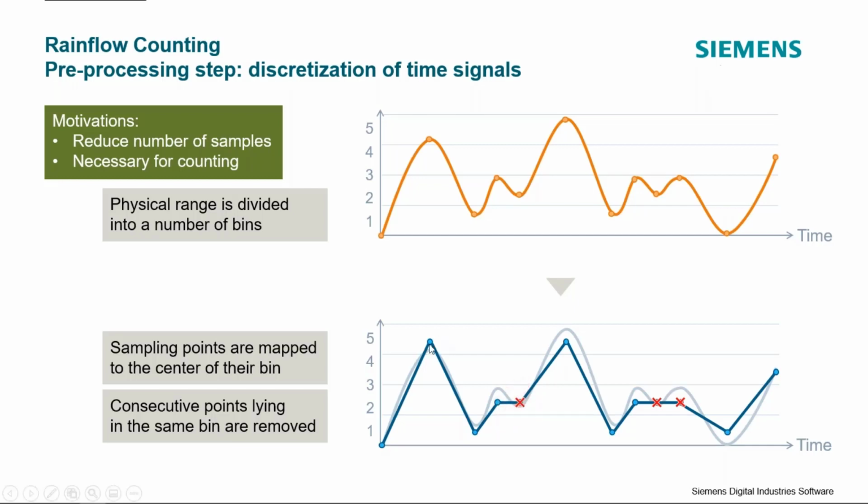It's important when you're doing a rainflow analysis to make sure that you have enough bins in order to not change the amplitude of these points by too much. Some common numbers that are used: I believe the standards describing this rainflow counting specify usually at least 64 bins. More commonly, I see people use over 100 bins when doing this type of analysis.